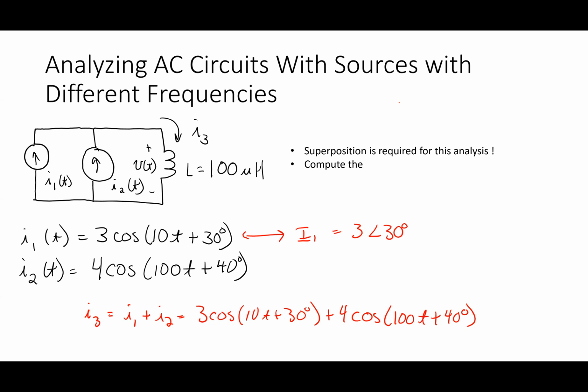An open, right? And we were talking about what kinds of sources when we did first order circuits and second order circuits? DC sources, right? So we were doing steady state. When we're doing impedance, we're doing steady state, all right? And I can think of a DC source as an AC source with 0 frequency, right? Because it's not changing. All right, so that's something we talk about pretty frequently. So if I had a DC source, I'd go through all the same approach, right? In fact, you've been doing impedance analysis at some level when you did first and second order circuits, when you did the steady state analysis, and you were using impedance without actually calling it that, okay?